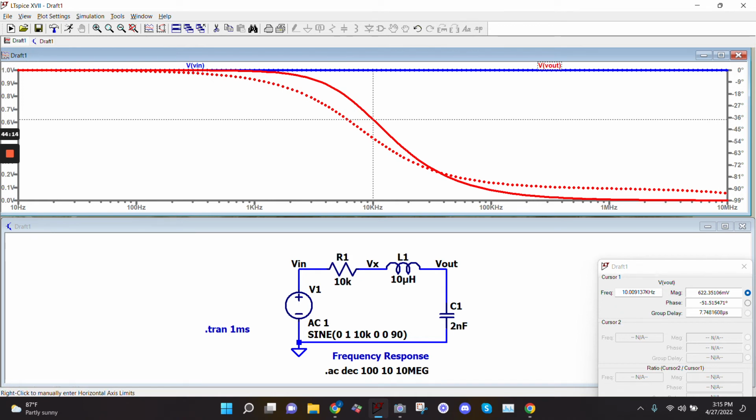Just briefly, if we have what's called a resonance frequency in these circuits where there's an inductor and a capacitor, that is the frequency at which this minus J and this plus J cancel each other out completely.